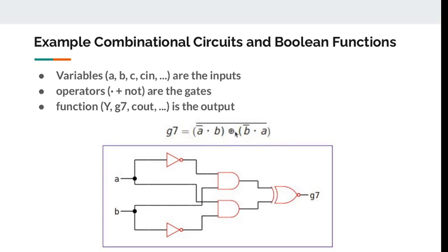And now for the rest of it, we have the exclusive OR, that's this function, but in this case we have a complement over the whole equation. So it's actually an exclusive NOR. We could have an exclusive OR here, and another gate here that represents the NOT. That's going to have the same behavior and represent the same function. And that's the output. So that's the G7 output that we need here. So again, that's the complete version of this equation that we can represent this way.